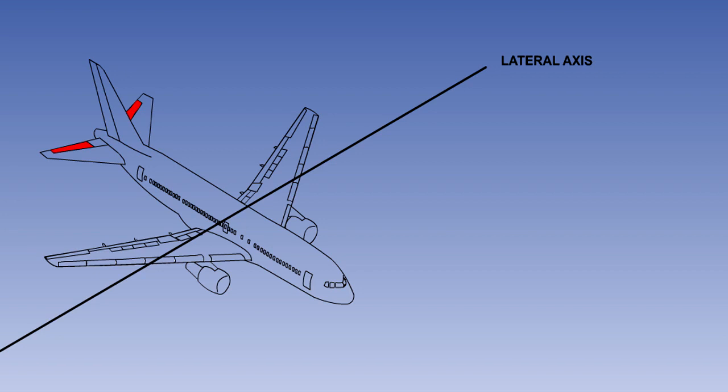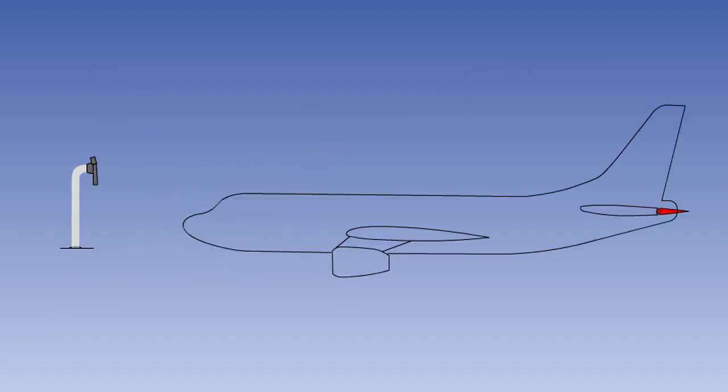The controls must be adequate to balance the aircraft throughout its speed range, at all permitted centre of gravity positions and configurations, and to give an adequate rate of pitch for manoeuvres. The pilot controls the elevators by the use of a yoke or control column. This control operates the flying control surface and is moved in a fore and aft direction by the pilot to control the aircraft.